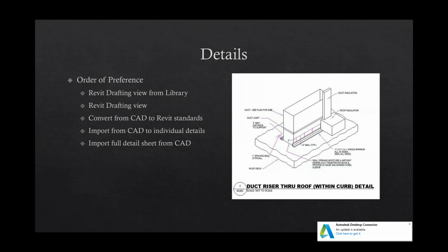That's a very good point. No worries, you're absolutely right. If it doesn't purge, yep. Ideally, purge catches everything, but there are some things it does not handle kindly, and you end up getting 5 billion different text styles and 5 billion different line styles. I have seen that because our CAD layers match our Revit line styles, it actually comes in pretty neatly, but you need to make sure you have good integration between both tools if both are being used. But yes, absolutely, any import.